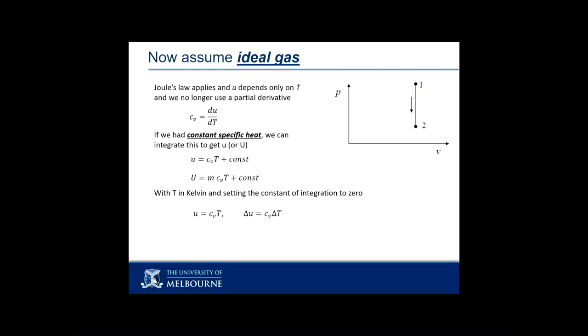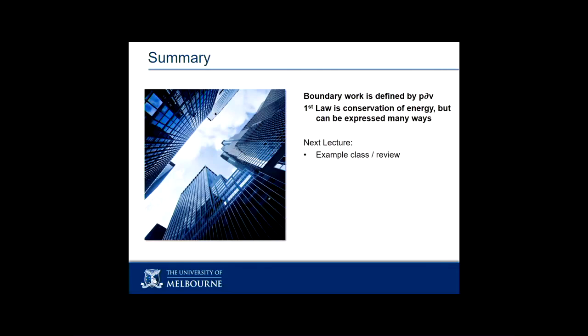All right? That bit there, for a perfect gas, an ideal gas, this is the big flag. Don't use this for steam. For an ideal gas, if I have the change in temperature, I have the change in internal energy. That doesn't require that I have an isochoric process. The CV definition came from thinking about an isochoric process, but now that I have the idea, I can use this for an ideal gas regardless of what's going on. dU equals CV dT. We will use that a lot.